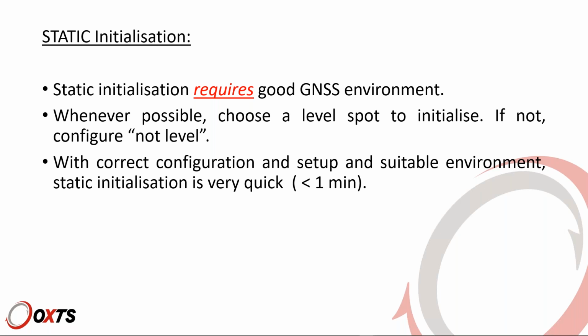If you have the correct setup, so basically a suitable distance between antennas, measured correctly, and a suitable environment, meaning good GNSS, then static initialization can be very quick, under a minute. It shouldn't take longer than that.